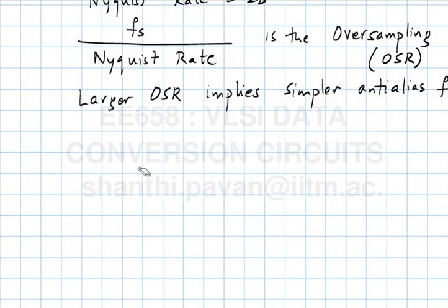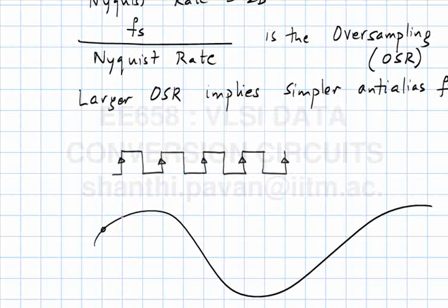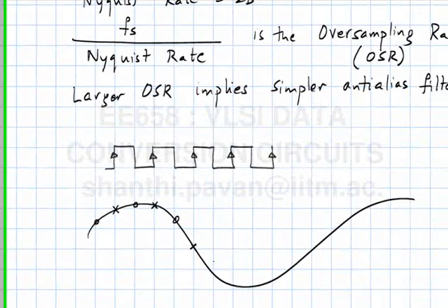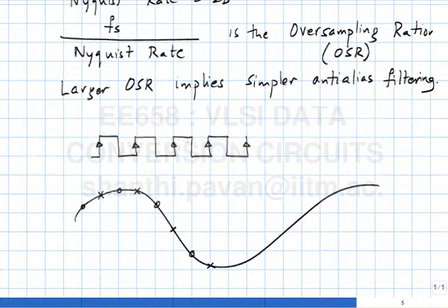So one way of doing this is to say, hey, let's say I am sampling at the rising edge of a clock. If I had two sample and holds which are slow, I can effectively double my speed. This is a signal, I need to sample it every time interval t seconds.